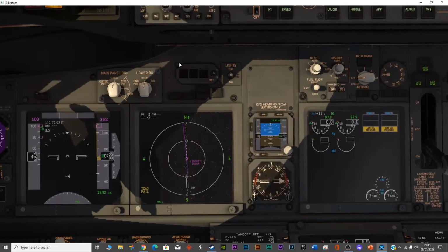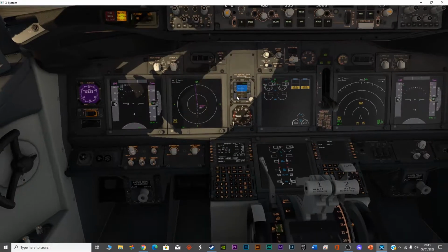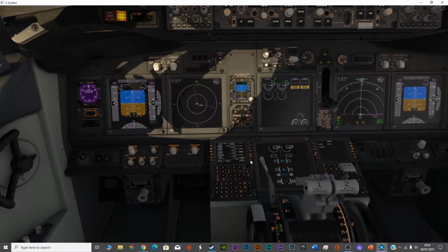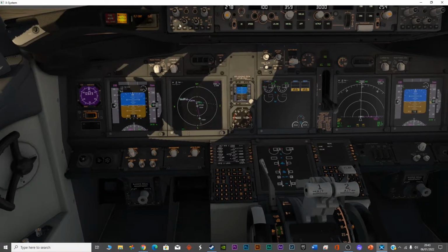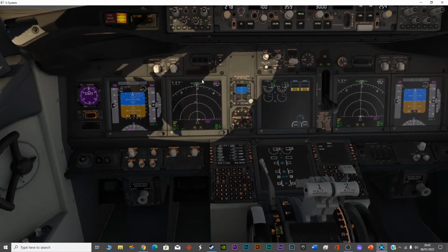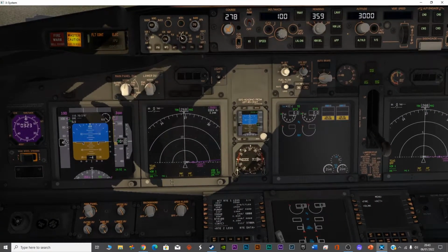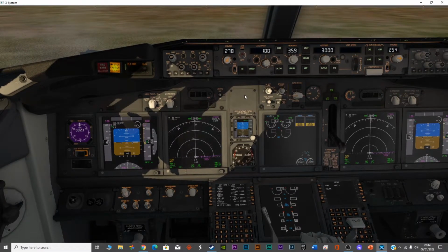Okay, so you can increase or decrease the range of the navigation display. And over here, if you go into this option, legs, and you keep on pressing the button step, it will take you through the complete flight plan. So this is the flight plan. Okay, so right now I will switch to map because this is the view that we'll be using on the navigation display during the flight. And let's set the range to 20 nautical miles. That's it.